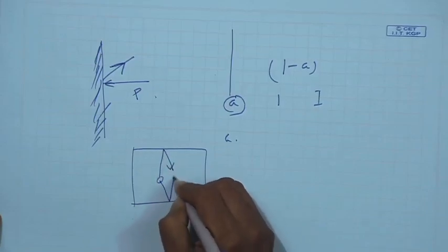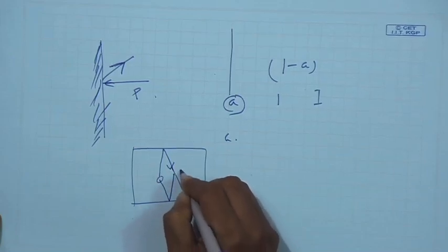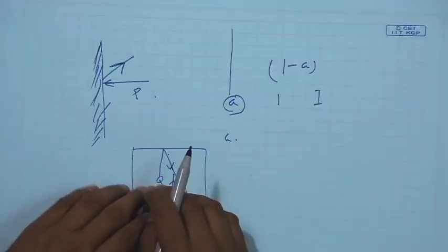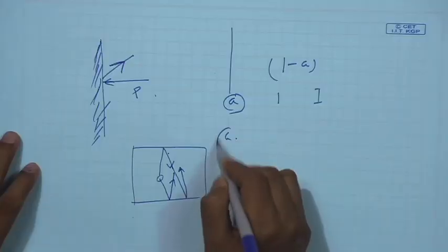Similarly, it will fall on this wall, then this reflection will fall on another wall, and create another reflection. All the reflections create a sound pressure level. If I switch on the loudspeaker in this room, for some time it is required to reach the steady state level of the room sound field. Since there is absorption, it is a semi reverberant field. So, the sound pressure level reaches a steady state.